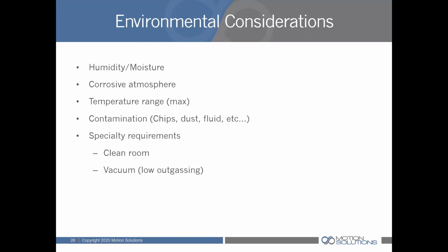And then we also have vacuum greases, which are low outgassing. We'll put these low outgassing bearings into very high vacuum, where a lot of times this will be a semiconductor application or similar, whereby whatever you're processing in the vacuum, you can't have any contamination from the grease of the bearing falling onto your part. So we have specialty cleaning that we specify, and special greases like a Krytox or similar low outgassing grease that we would apply.